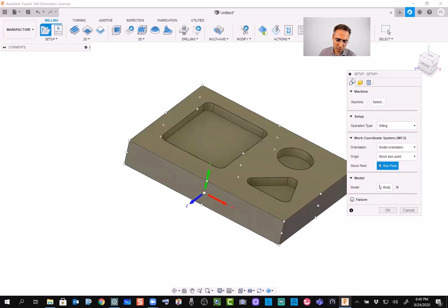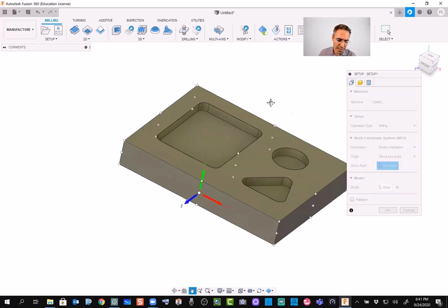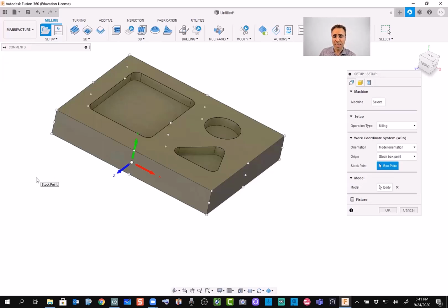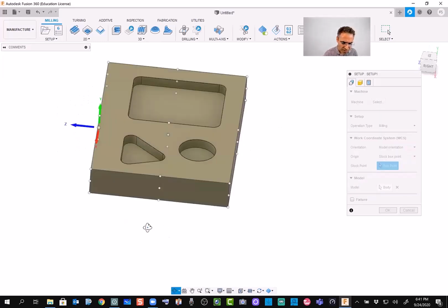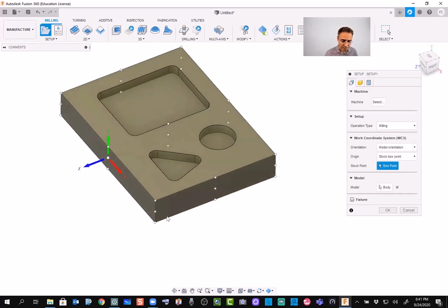The first one is very important. The first tab is where we basically set our XYZ. We need to select an XYZ, so when we put this box in our machine, we know where the origin is. We need to tell the tool, hey, this is the 0 point, okay? So I need to select a point that later I can recognize as the 0 point. It's bad to have it at the center because we need to do measurement. It's very common to select one of these corners as the origin, because we know where it is.